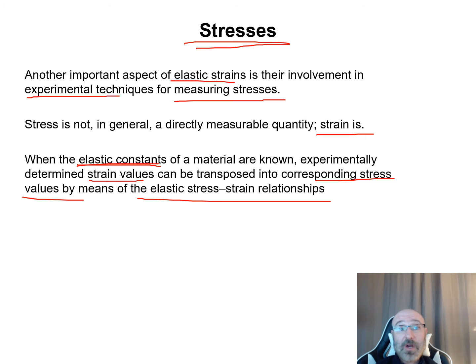Look at that stress-strain curve, and maybe we measure our elastic modulus off of that. One, maybe we're comparing to make sure that yes, it is the material that we say we put in there, and that it has the values we'd expect from our lookup, from our material properties or from our manufacturer. Or maybe we do that experimentally and we find, okay, this is our elastic modulus right here.